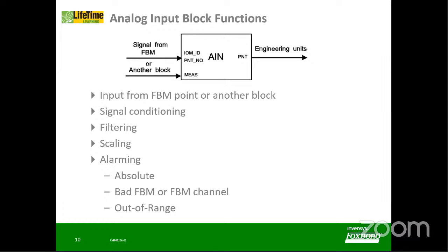But always remember, as I have mentioned, inside a CP you may have more than 6,000 or 7,000 function blocks. So you cannot adjust one block, one parameter at a time. They all will be done in bulk, and that's what we call bulk generation. While creating a bulk generation, the common parameters will be created in a bulk manner. Once the bulk generation is complete, if any specific requirements are there from a customer for an individual loop, you can change those parameters at a later stage also.